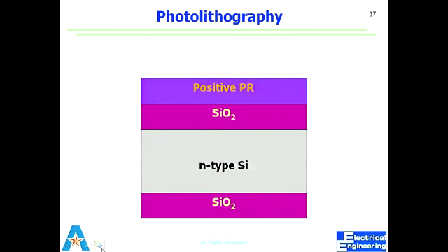Coating is, we use that chuck to hold on to the wafer. We rotate it at 4,000 RPM and we apply a liquid in the center of the wafer. First we put the liquid in the center of the wafer and then we spin it. Think about it. What will happen to the liquid? It will fly off.